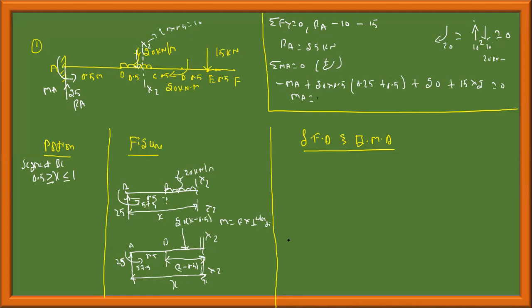Now, for shear force, F is equal to the summation of forces in the y direction. From the section, force acting upward toward the left-hand side is positive, and force acting downward is negative. For bending moment, a smiley-face (sagging) moment is positive, and a counterclockwise moment from the section is negative.